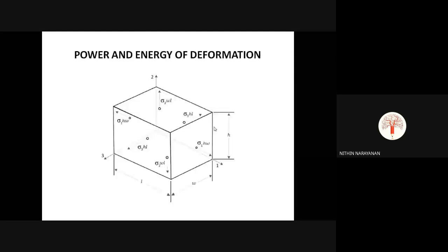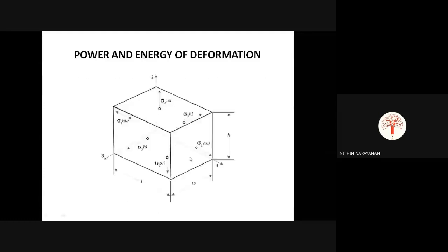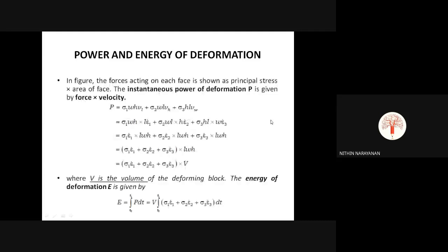Okay, so with L, W, H we can find the area at each face. This area will be W into H, this area will be L into W, the top area will be W into L. Okay, the left area will be L into H. So we can find all the areas. So in the figure the force acting on each face is shown as principal stress into area of face. So we can find out the force.